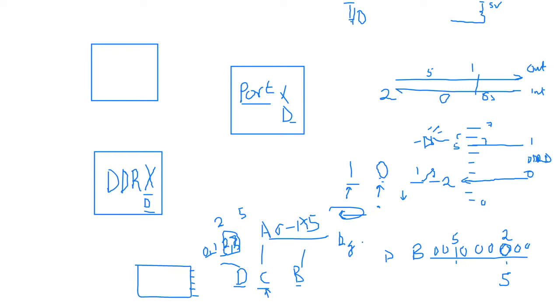So we've set the direction. If it is an output and we send a 5 to it, it means that pin just gets 5 volts assigned to it, which is a 1 or a high, right? If it is an output and we send a 0 to it, that pin just gets 0 volts, which is a low signal that we are dealing with.